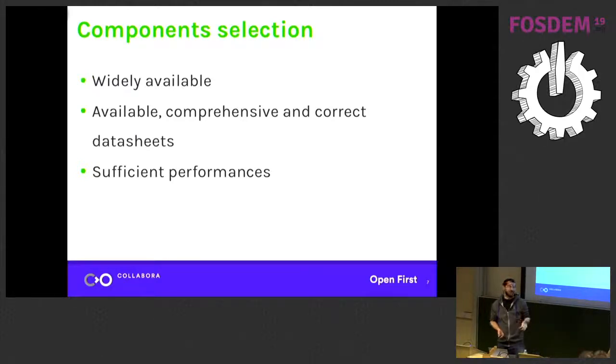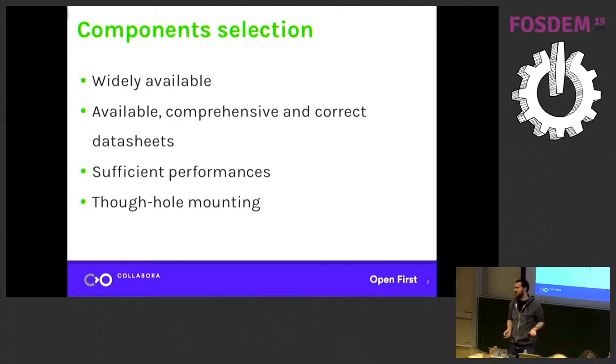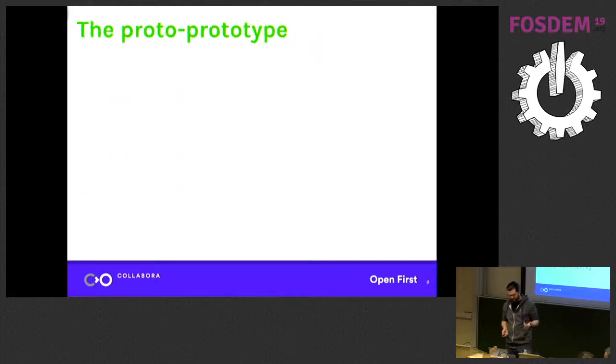And a small one that is rather really personal, but I really prefer through-hole mounting components. Don't forget that I mostly work with electron tubes, which are big devices, and all the components surrounding the tubes are high voltage capacitors and power resistors. So I'm used to working only with rather big components. Of course, if you're using a microcontroller in a TQFP package, you won't be able to do that. But for someone who has not real experience in soldering, starting with through-hole components is really easier, way easier.